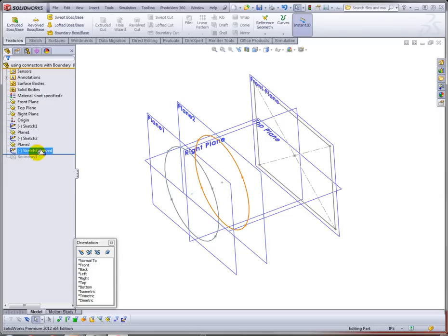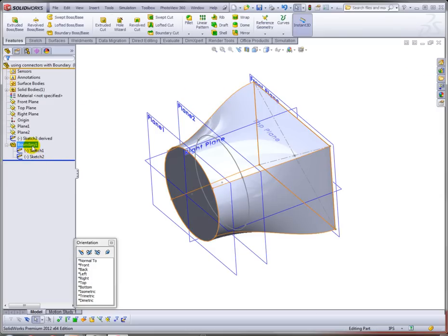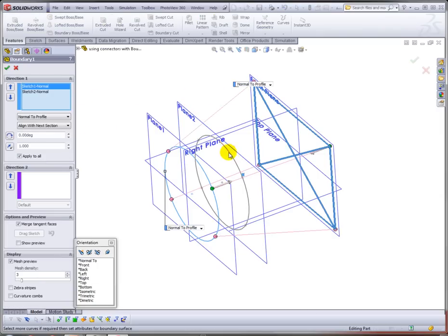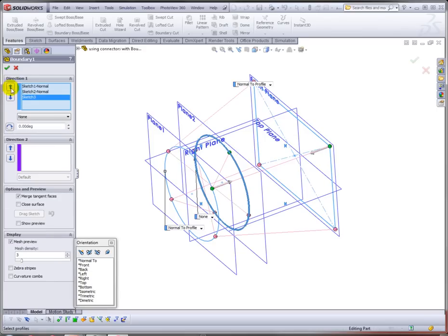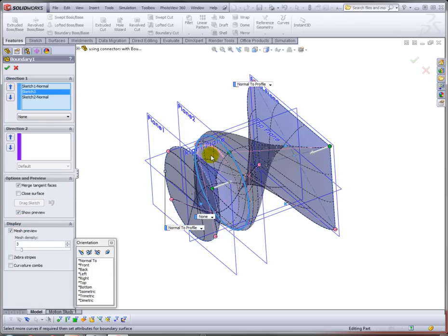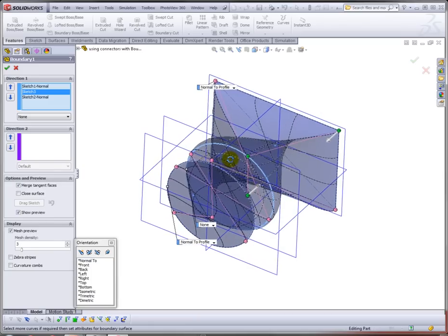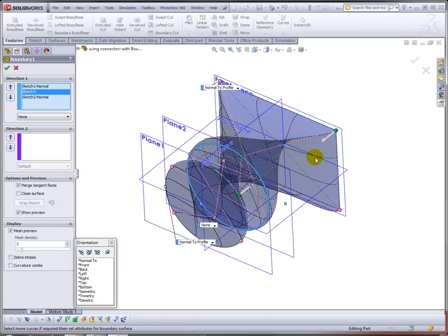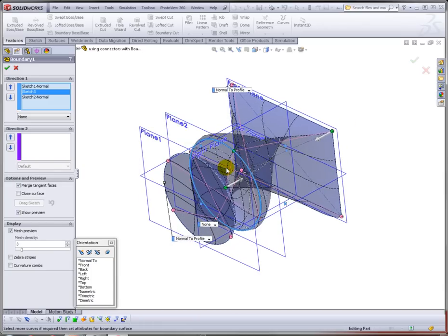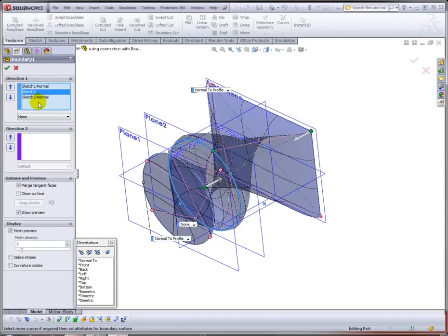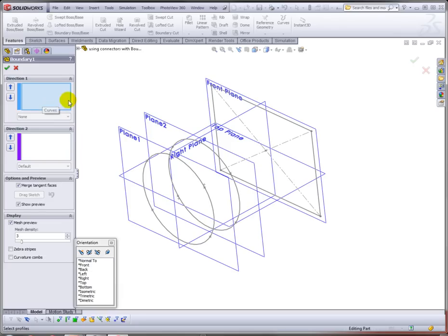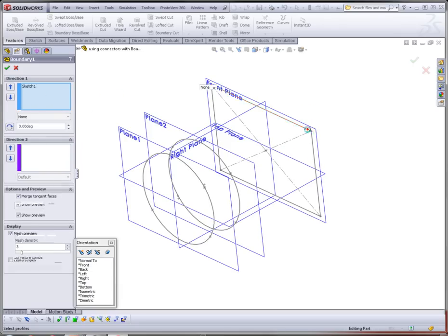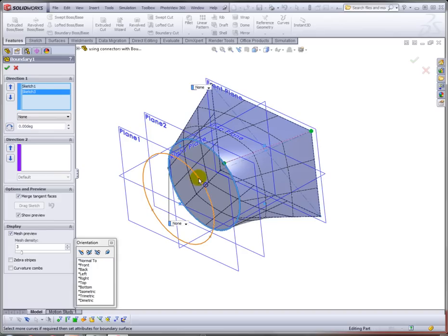And so now when I go back, roll forward to my boundary feature, I can edit it, and then I can include this sketch. Now, I'm going to warn you here, because we've created connectors, then it's user-created connectors. It really kind of gets screwed up in its twist order. So really the best thing to do here, I'll just be frank with you, is just reselect your profiles. So I'm going to clear all of them, and by doing that you're going to give it the proper order of how it should loft.